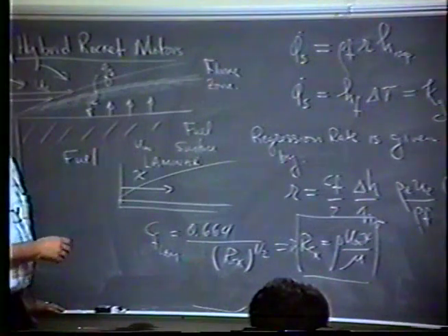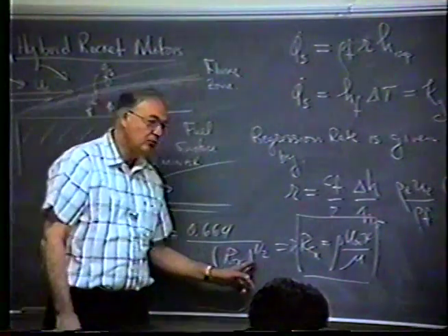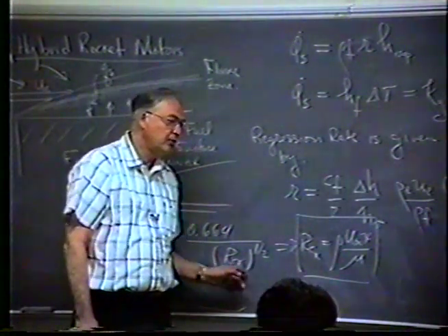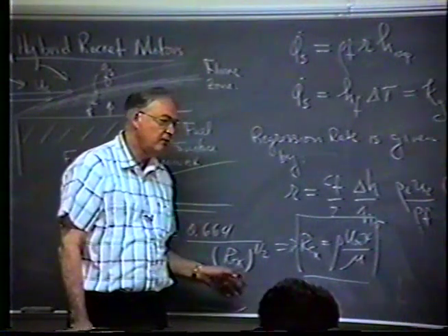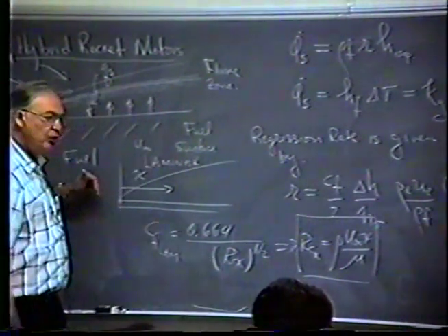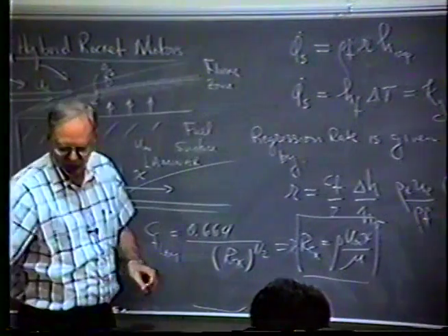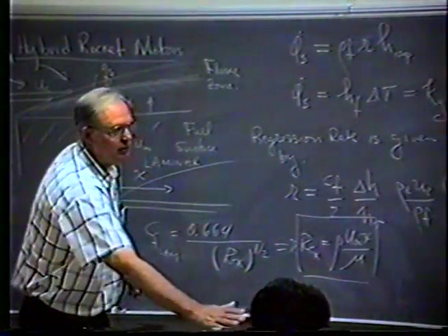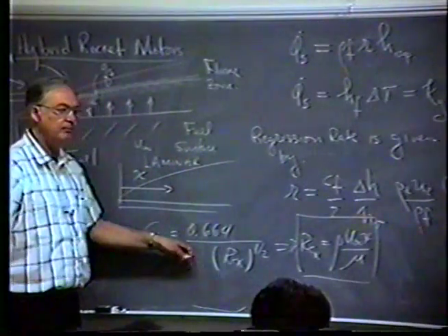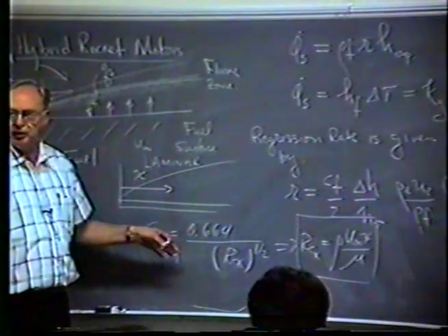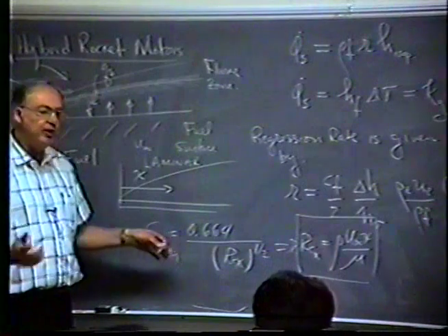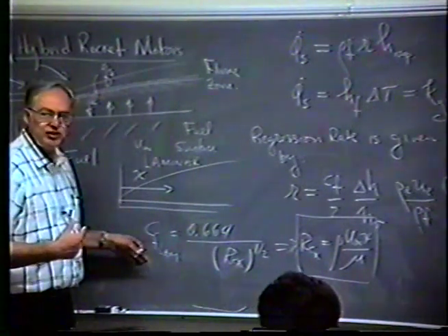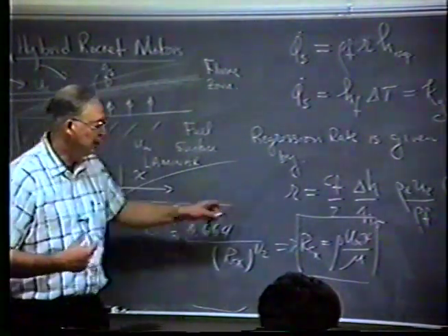Decreases parabolically. Inverse to the square root of the distance. So the shear stress coefficient on a flat plate, this plate right here in front of us, decreases as you go down the plate by that rule. Anybody with me? Okay, so then what relationship does this have to this expression?